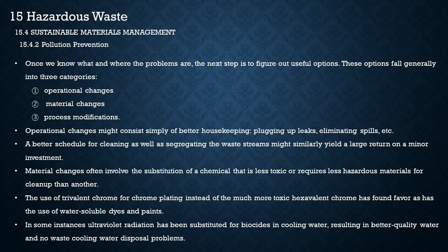Material changes often involve the substitution of a chemical that is less toxic or requires less hazardous materials for cleanup than another. The use of trivalent chrome for chrome plating instead of the much more toxic hexavalent chrome has found favor, as has the use of water-soluble dyes in paints. In some instances, ultraviolet radiation has been substituted for biocides in cooling water, resulting in better quality water and no waste cooling water disposal problems.